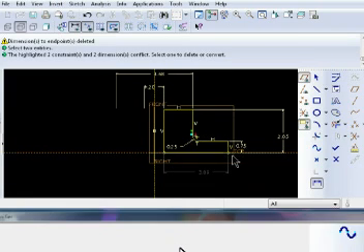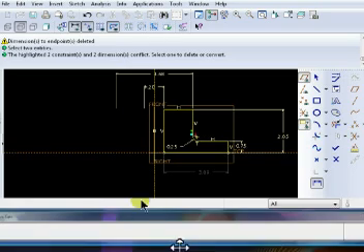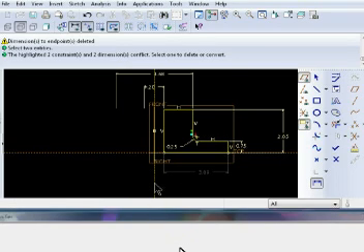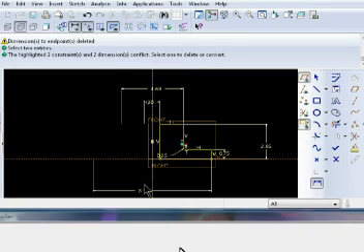Finally, for this line's diameter dimension I want to show you a different way that you could create a diameter dimension. You could do this backwards, where the two left mouse clicks are on the center line and one only on the line itself. So let's start. Left mouse click on the center line, left mouse click on the line, another left mouse click on the center line, and a middle mouse click where you want to place your dimension. It works.